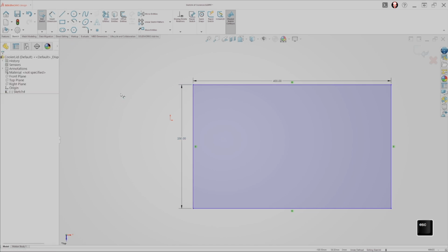Like I've mentioned in Autodesk Fusion courses that we've produced, the escape key is your best friend. You may not realize that you are still inside a command or a command is selected in the background. So if you try and use other features while an old command is still active, you can actually make mistakes or affect your file unexpectedly.